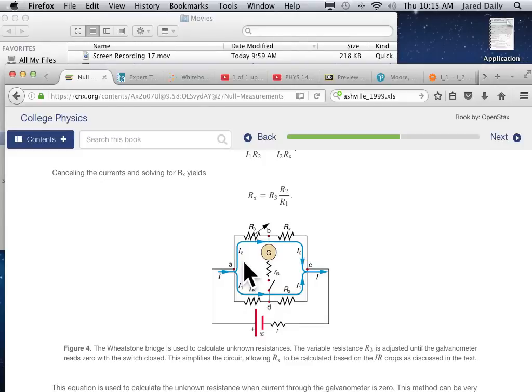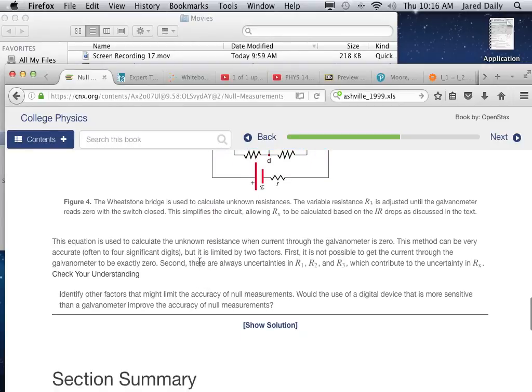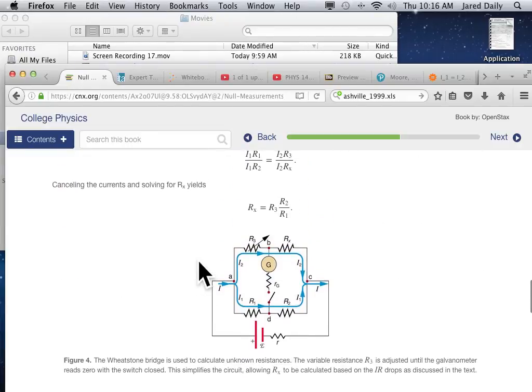The idea here is to measure a resistor that goes between the two paths, resistance G, and you put a little, let's see here. No, sorry, that's not the idea. This is a different setup than I was thinking. The idea is to put your galvanometer in between here. So this galvanometer is designed to measure a current that's going between these 2 points. Now, if the point B and point D have exactly the same voltage, there will be no current. Absolutely no current through here.